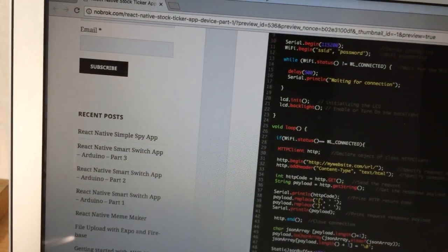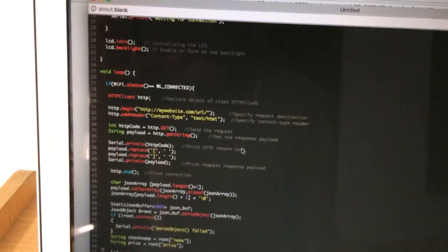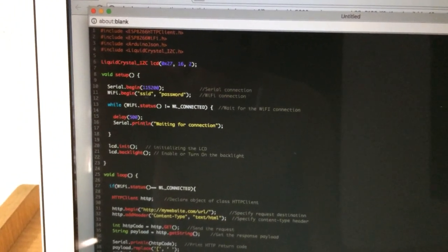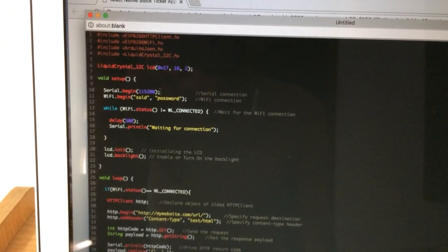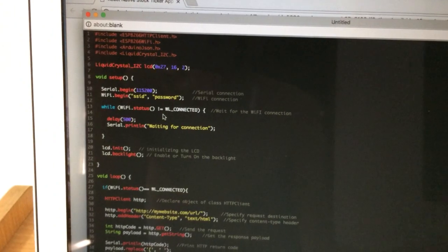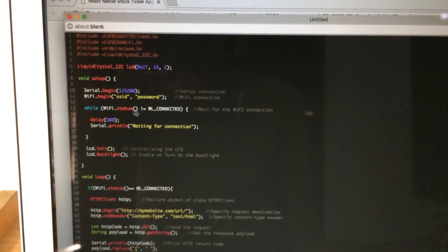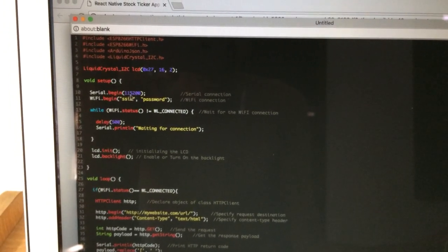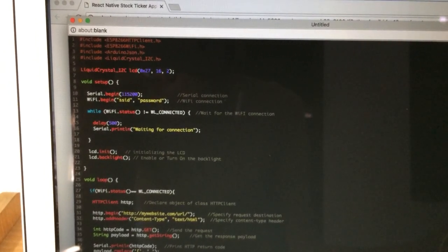And so once you instantiate the LCD library, then we just mention the serial communication rate so that we can use the monitor to print the output. The monitor, that is not the LCD, just don't confuse the monitor with the LCD. We have a separate option for printing things on the monitor. So this is the speed, bits per second, to use to print on the monitor.